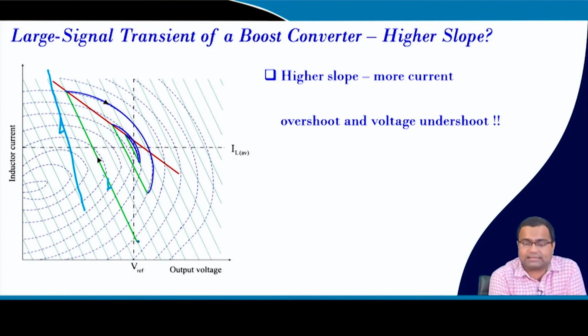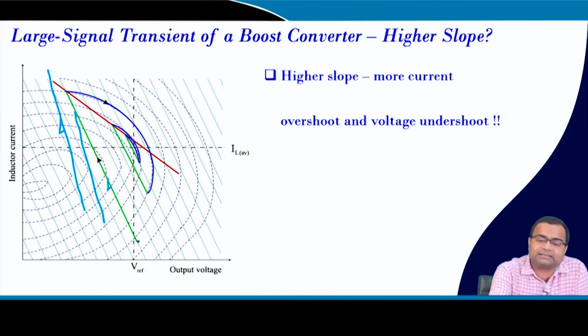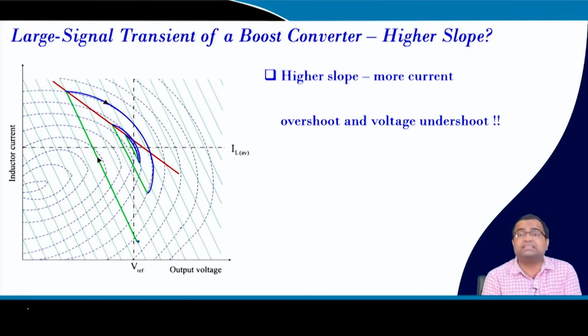As a result, suppose if this is your switching surface, that means you are actually reversing the switching logic, and this side, if I take this trajectory here, it is going away from here, right. This is the on state trajectory, and this side also the trajectory is going away. That means, this is a scenario where we are getting a rejective region.